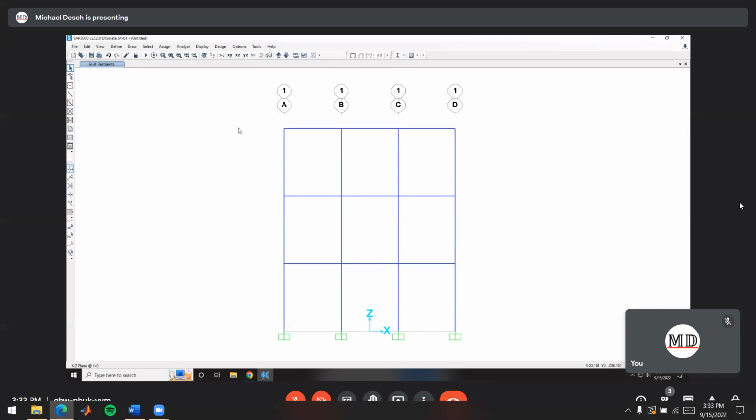When we draw a uniform load in a 2D frame like this, it crashes the program. I don't know why. It works fine in 3D. It works fine on the 1D beams like we did last week, but when we do it in 2D, it breaks. They know it's a problem. They fixed it in the next version of SAP.